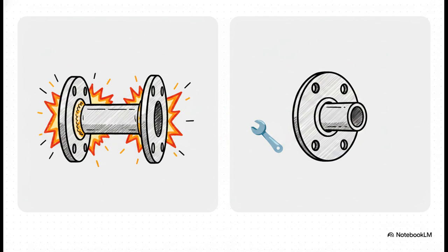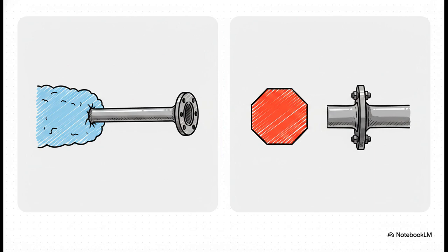It's strictly reserved for lower pressure situations where you just don't need that massive heavy-duty durability. Next, we've got the long welding neck and the blind flange. Out in a plant, equipment is often wrapped in thick layers of insulation. A standard flange would just get completely buried in that stuff.